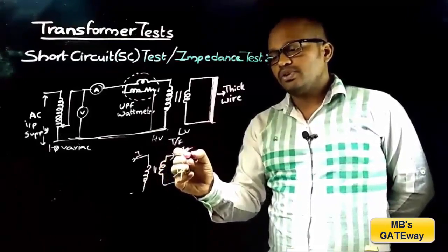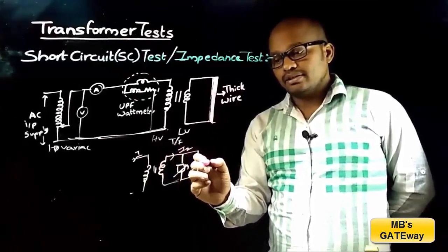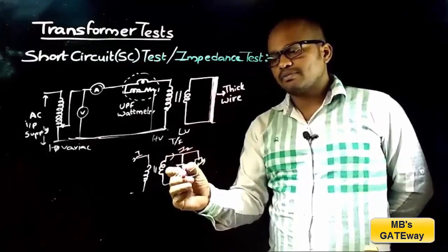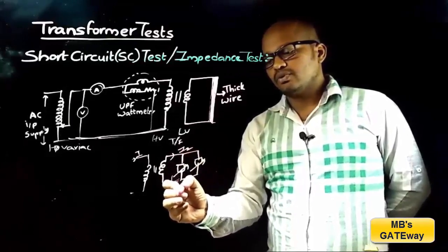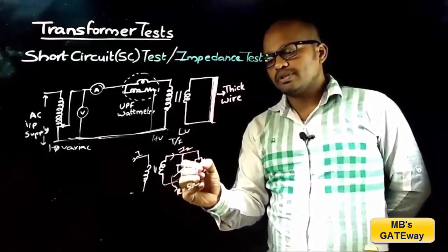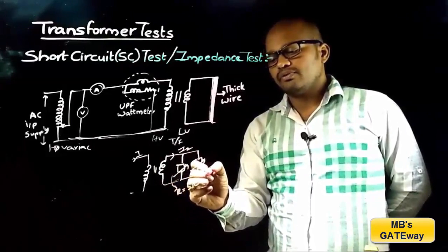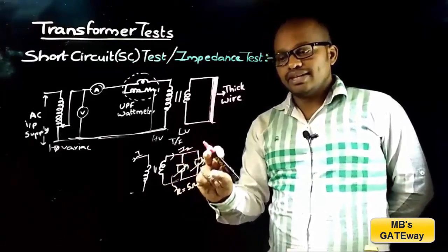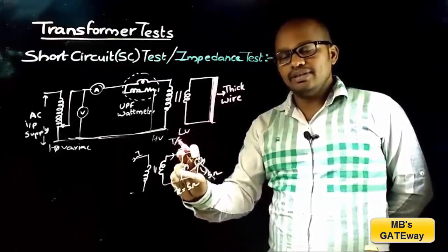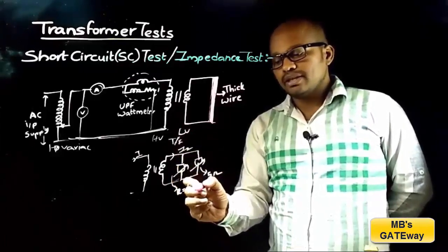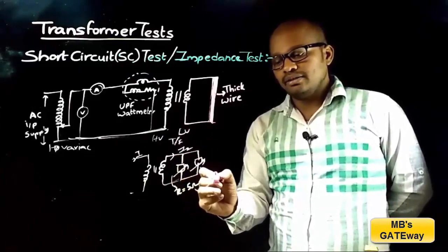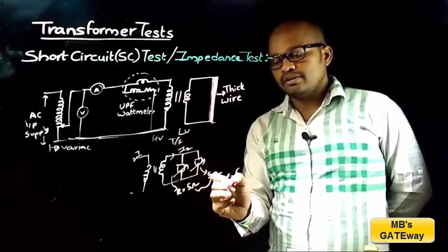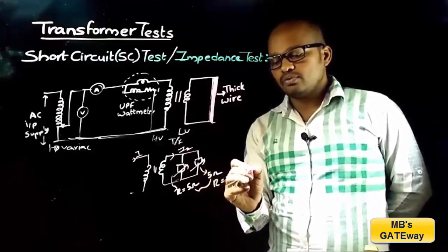And now if load is increased, that is, here load is connected in parallel to the existing load, and let us suppose this load be resistive load of value 5 ohms. And when load is increased, that is, when extra load is added in parallel with the existing load, observe that as these two are connected in parallel, the effective resistance value is 5 into 5 by 5 plus 5, which is equal to 2.5 ohms.